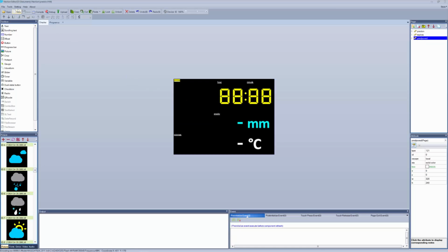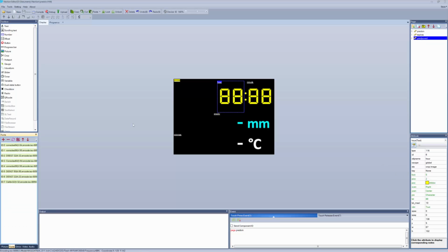For the fonts, I showed you how you can generate the fonts, and once you do that, you just select the font ID. Because it's a rather low resolution display, my suggestion is to use some readable fonts, some sans serif fonts. If you're gonna have a table of values, then consider using monospace fonts, because then they're gonna be all aligned, all the digits are gonna be aligned one under the other.